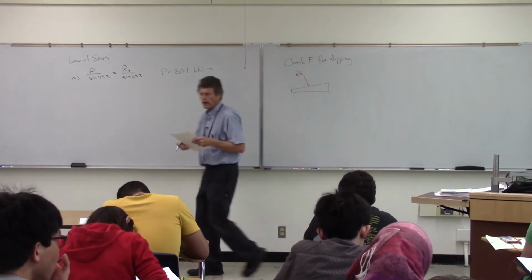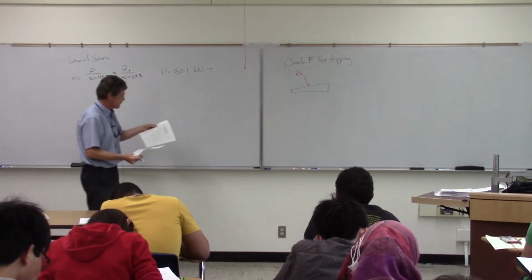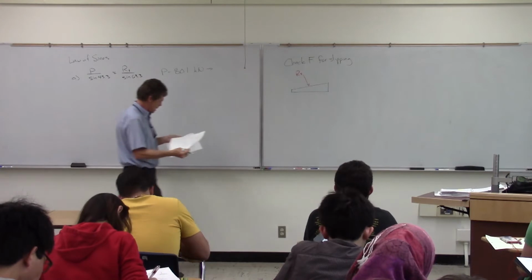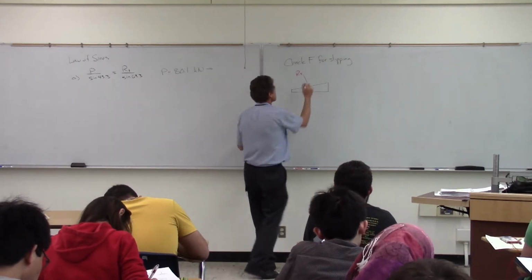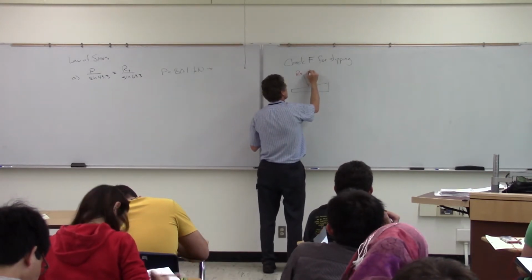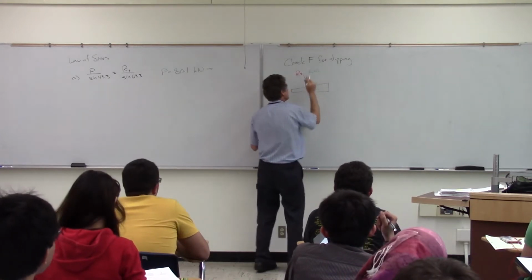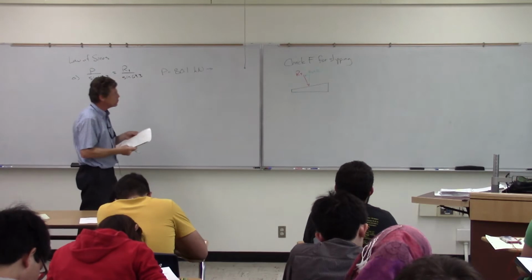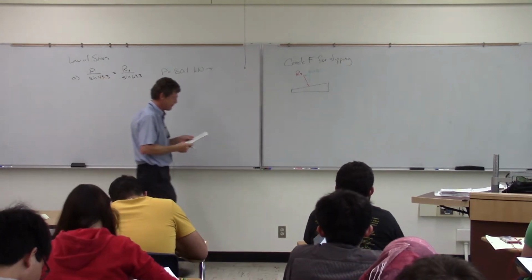So again, we'll go ahead and use our Newton's third law. So we're going to take the R2 that we just got done from the free body of E there. And then that angle will be the friction angle plus the wedge angle of 10 degrees.